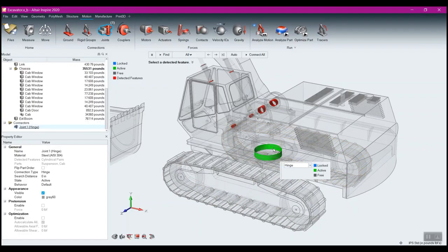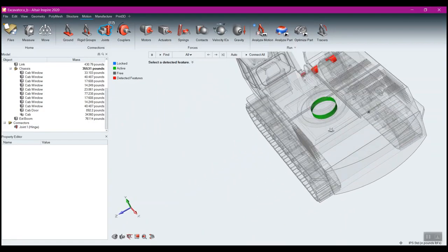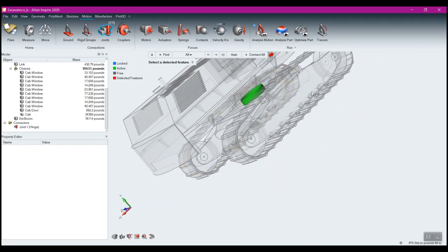So the other types of joints that we have: a cylindrical joint is going to allow rotation and translation. So think of a cylinder inside of another cylinder. Translational allows only translational motion, so no rotation whatsoever. And then ball and socket is your standard ball and socket. So imagine a ball and socket joint, and that sort of rotation in multiple directions is allowed. So you want to make sure that you define not only your joints, but you define them appropriately.